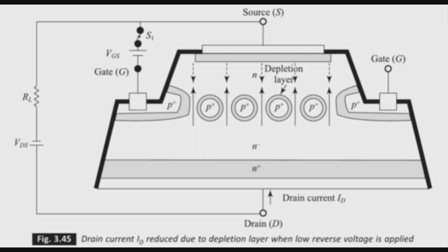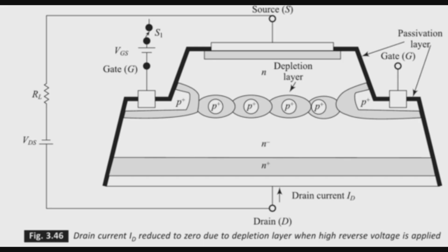And this is exactly the point where the static induction transistor becomes easy to understand. A SIT operates on the same fundamental principle as a JFET: a PN junction gate, depletion mode operation, and current control by restriction rather than switching. The difference is not the principle, it is the scale. A SIT uses a vertical, deep channel structure, allowing operation at much higher voltages and currents. For this reason, it is technically correct to say that a SIT is essentially a power JFET.